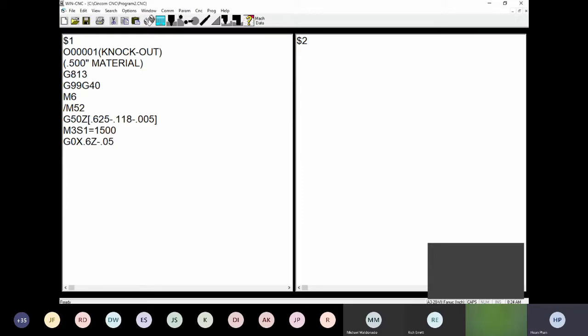And the next thing we're going to do, as we talked about yesterday, we have a function called tool cut-off break detector, and we use a sensor at tool number 19. We come in to check that the material is already retracted, or the part is separated from the machine already or not, to make sure our cutoff is not broken and it is safe to start. So I put it right here, the M51.